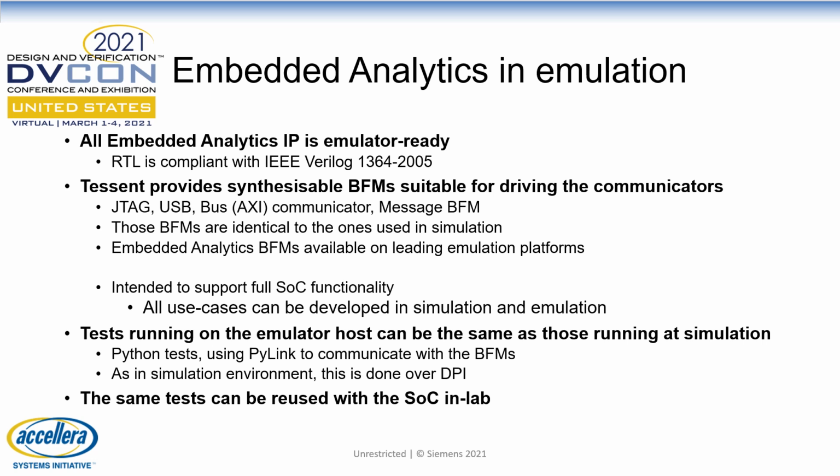Integrating and using embedded analytics in an emulation environment is as simple as using it in a simulation environment. All embedded analytics IP is emulator ready, written in standard Verilog. Tessent provides synthesizable BFMs suitable for driving the communicators, whether this is JTAG, USB, or AXI communicators and others. Those BFMs for emulation are identical to those used in verification, so transition from one to the other is straightforward.